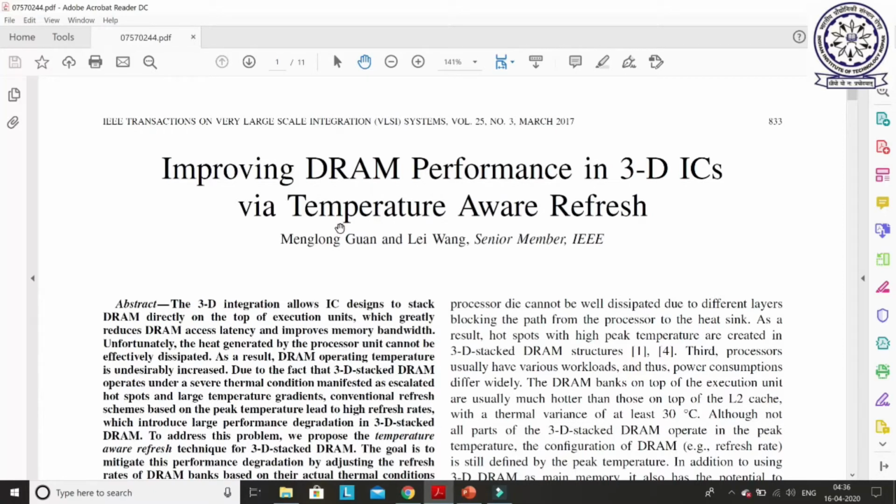I think I have covered this part while I was explaining embedded DRAM before midsem. So that part is also important. The main advantage of using DRAM as last level cache is its capacity, because when it comes to last level cache, it has been found that capacity is more important than latency.